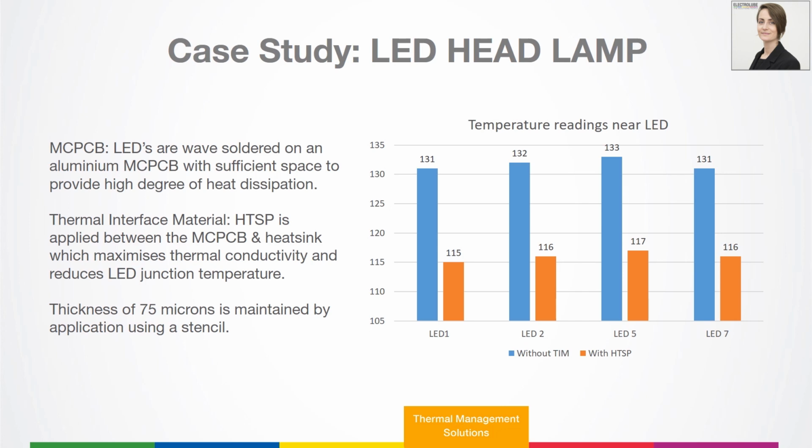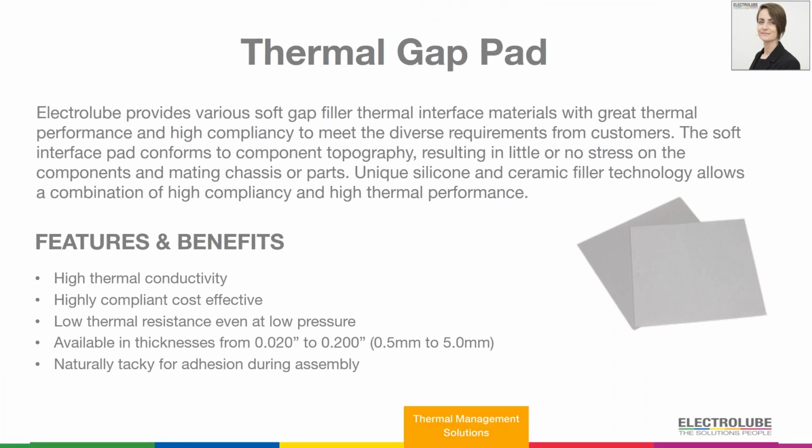application. So thermal gap pads, they're soft materials. They are very compliant. So when you feel them, you can squash them down, you can make them fit to the contours of the interface. But in order to achieve that, you do need to have some pressure there to make them squash down into all of the gaps. They don't impart any stress on components because they're so soft, and they're easy to apply. Simply cut to shape and put onto the device, place them on. So they're easy to rework as well. Thicknesses are quite a lot higher than a thermal grease because you're starting roughly around 500 microns.